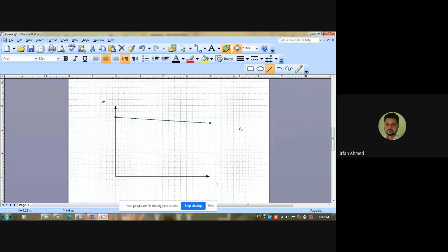This one is a characteristic with only the armature resistance, no external rheostatic resistance in the circuit. In that case, this characteristic will be called the natural characteristic of the motor.